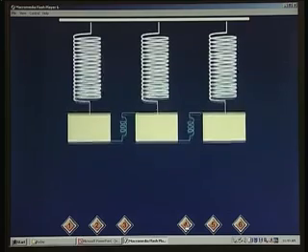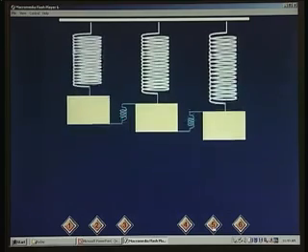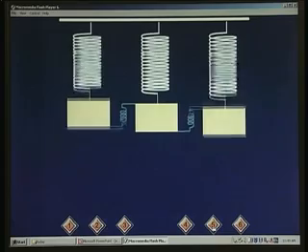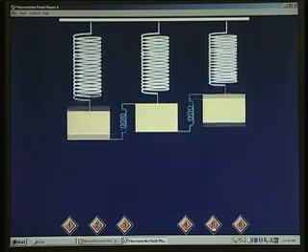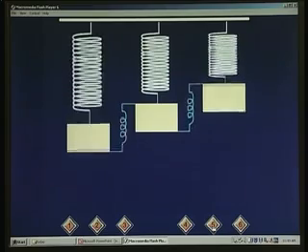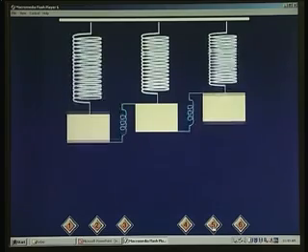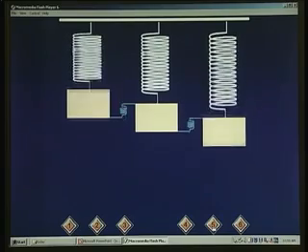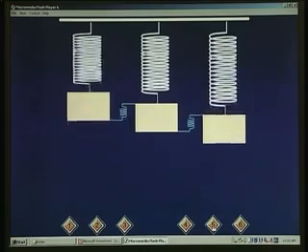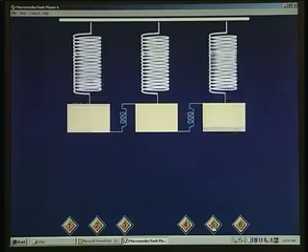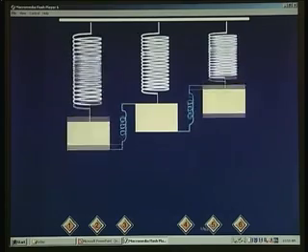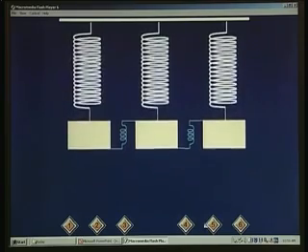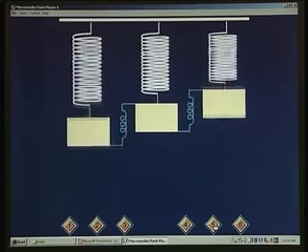For example, it can oscillate as follows: the center mass is stationary and the left and the right mass are oscillating in opposition. Note that the frequency of oscillation is now more than the frequency of oscillation when all the 3 were oscillating in unison. Why? Because now the effect of the coupling spring is also coming into picture. Effectively the spring constant k has increased, so your frequency is more. Compare it with this oscillation. Okay, this is slower. So this is the second mode of oscillation.